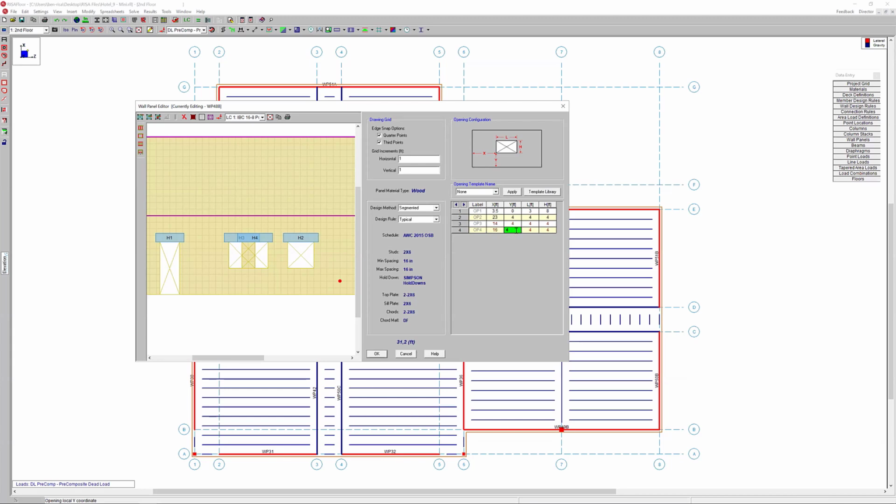If I shift this as well, maybe instead of shifting it right or left, let's go a little bit wider, like 30 feet. So I shift it out here. Now let's delete this guy, delete mark lines. If I shift this up to, let's say, 8 feet, you can also see that this opening intersects with the diaphragm. So I get the same warning because I have the same issue. I can't have an opening that is intersecting or crossing over a diaphragm either.